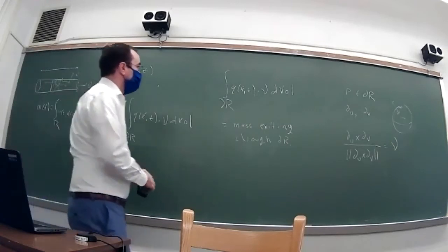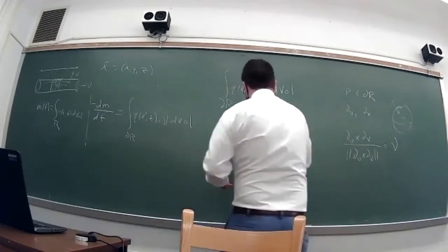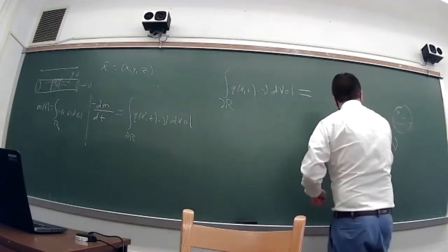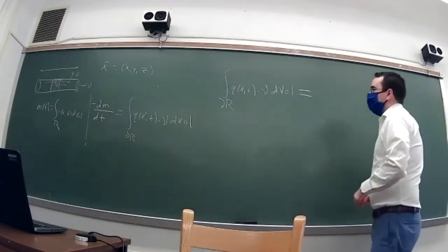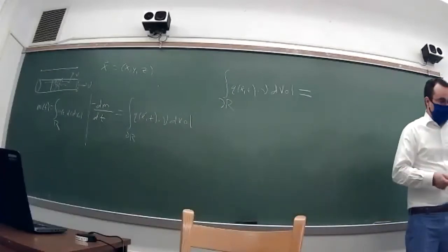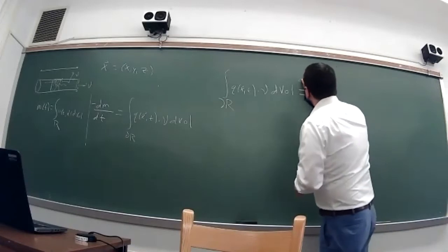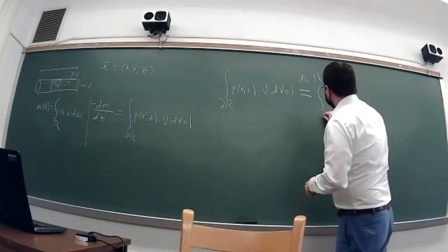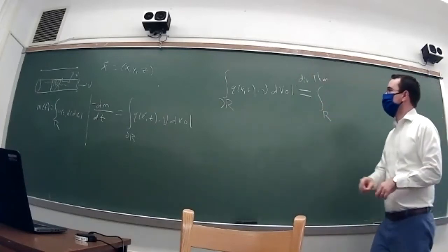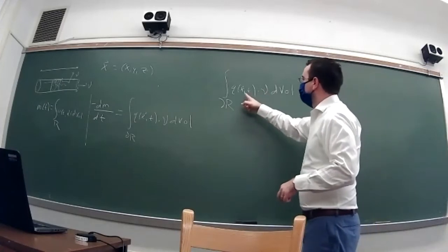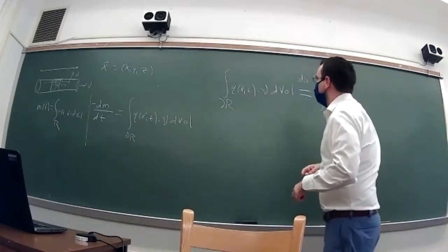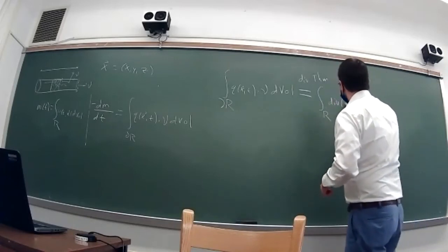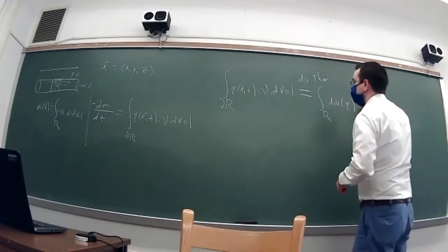Now that we've got this going here, you should use the divergence theorem, which is like our multi-dimensional analog of the fundamental theorem of calculus. What that tells us is that the dot product of this vector with the normal should be the divergence of the vector q over the surface.